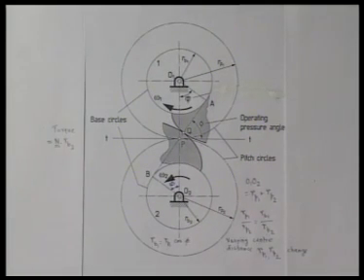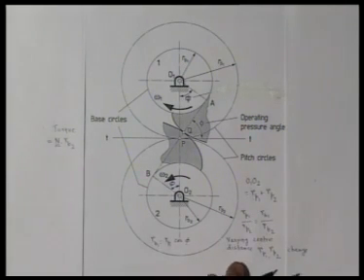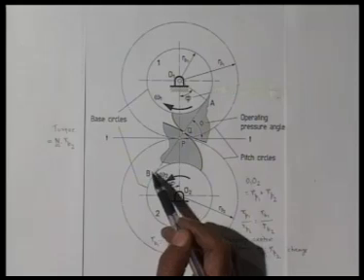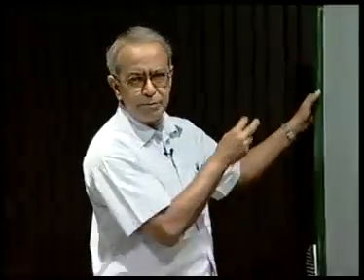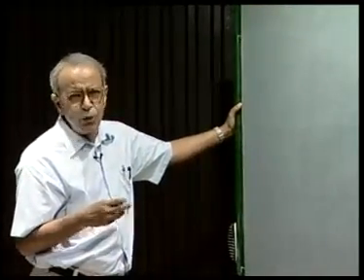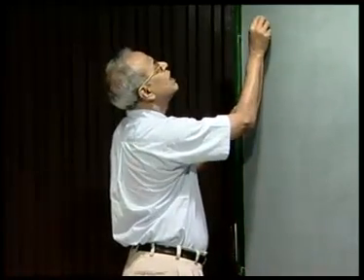And the fourth advantage, as I said, will be explained later when we will be able to show that the involute of a straight line is a straight line. That is, for a rack, to maintain conjugate action with an involute profile, the tooth profile on the rack will be straight like a trapezium, as we have shown earlier on the board. Because involute profiles have all these advantages, as I said earlier, they are almost universally used in mass produced gears. And as a consequence of this mass production of involute gears, they have been standardized. There are various standards, but I can mention some typical standards which are more commonly used, like the British standard for involute profiles.